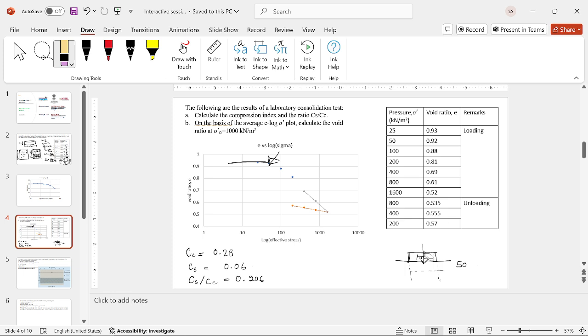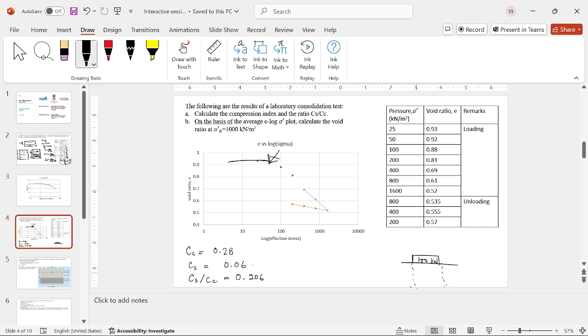For example, let's not talk about the history. Let's say that I have a soil and I have a load of 100 kilonewton on it. And I know for a fact that this soil will act as over consolidated soil when I put on a load less than 100 kilonewton, because right now there is a 100 kilonewton load on it, isn't it?